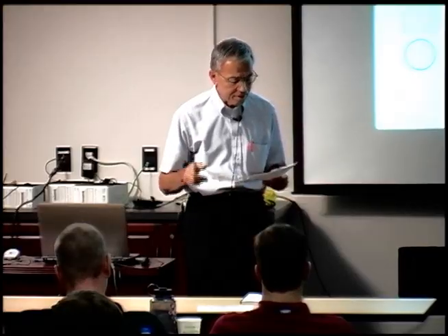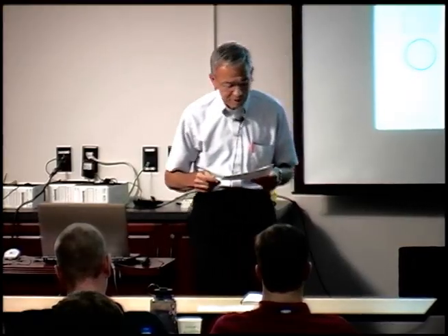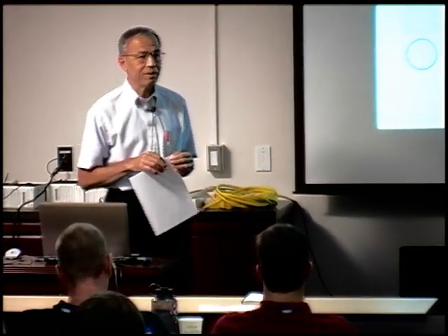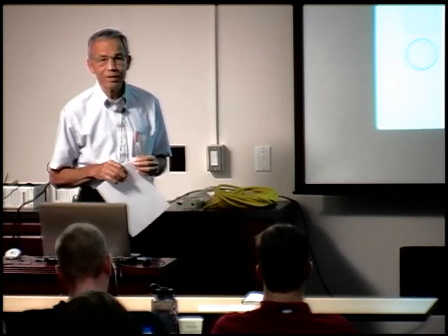It appears that probably the drivers will be reaching bearing earlier than otherwise for 3 of the pile types. Now, a question that has been talked about among some of the people here is, what is this LRFD going to do to our pile lengths?